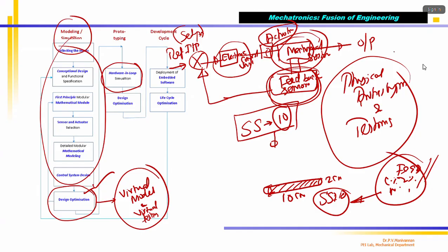So in that case, you said that you should have 97% of Fe, correct? You wanted to have 2% carbon and, say, 0.5% nickel, something like that. You are adding 0.5% or 0.2%, something. This material you are going to weigh, correct? 97% Fe, I am talking about around a 10 ton or 20 ton furnace, correct? So coal you are going to add. When you do all this, exactly is not possible, correct? You will not be able to add exactly 0.5, and the purity of the Fe, iron ore, the purity of the carbon contents or the purity of the nickel, all these things is not possible. You are trying to get as close as possible.